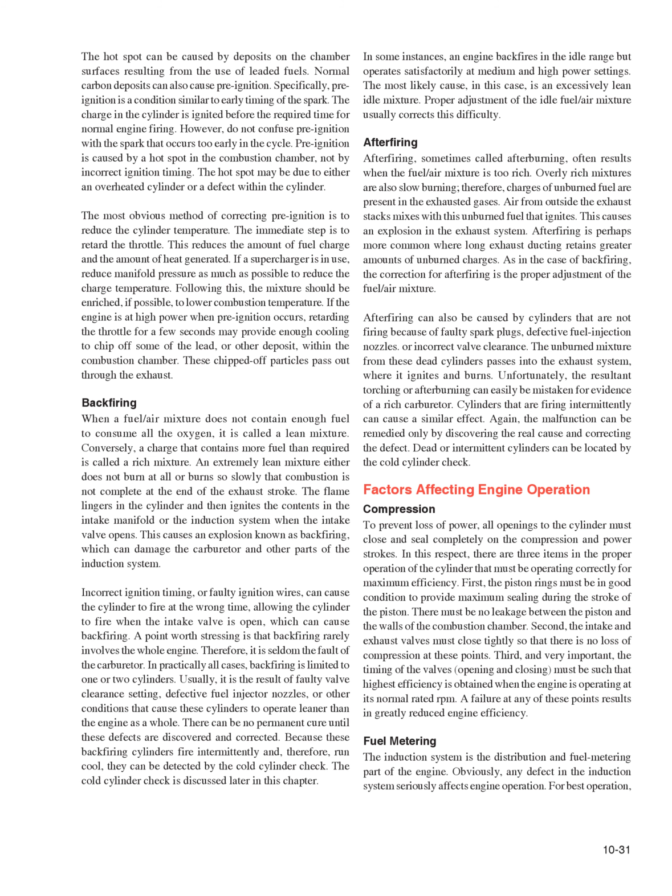Second, the intake and exhaust valves must close tightly so that there is no loss of compression at these points. Third, and very important, the timing of the valves, opening and closing, must be such that highest efficiency is obtained when the engine is operating at its normal rated RPM. A failure at any of these points results in greatly reduced engine efficiency.